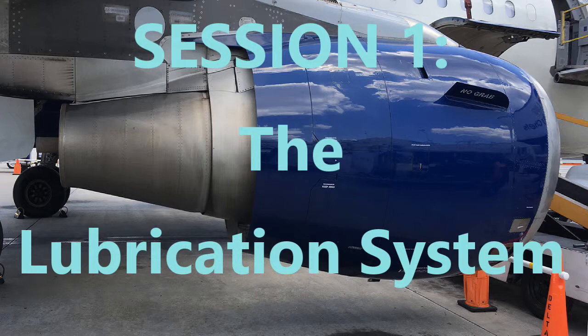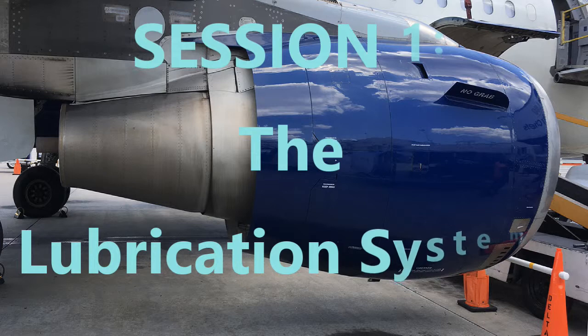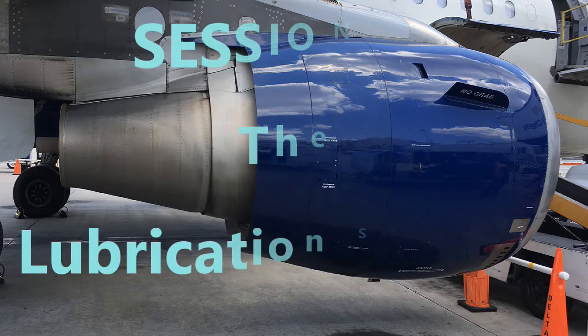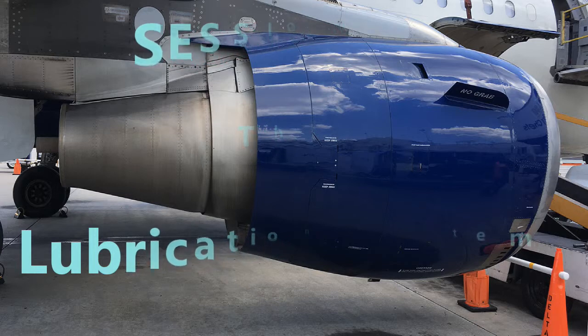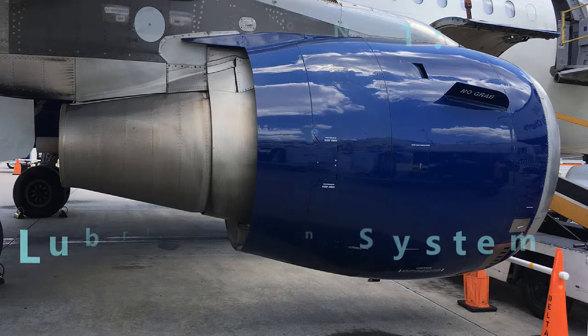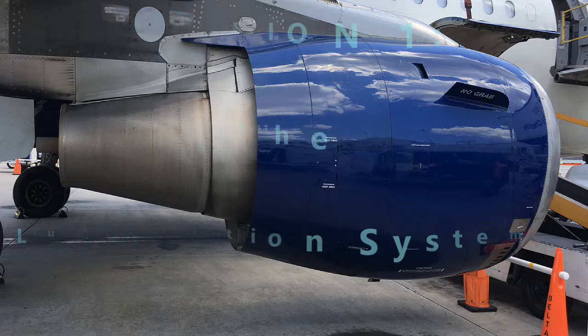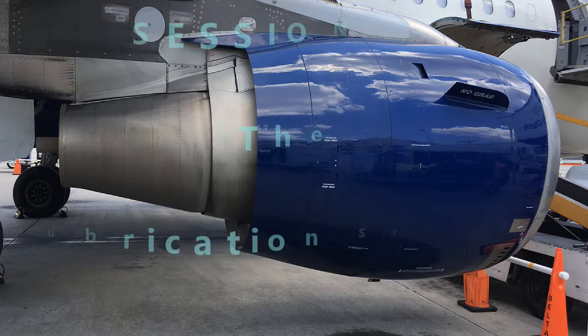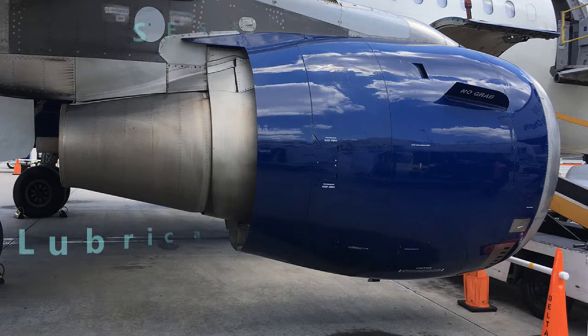All right, so we have the supply pump to pressurize the oil to go to the engine bearings, the accessory gearbox and the transfer gearbox. Well, now we've got to remove some of that oil, getting it back out. And here's where we come into the 4 scavenge pumps. So you have 4 scavenge pump elements that take away that oil from the engine bearing sumps and the gearbox, and it's going to be returning that back to the oil tank, and it's got to cool it. So just remember, it has to cool that.